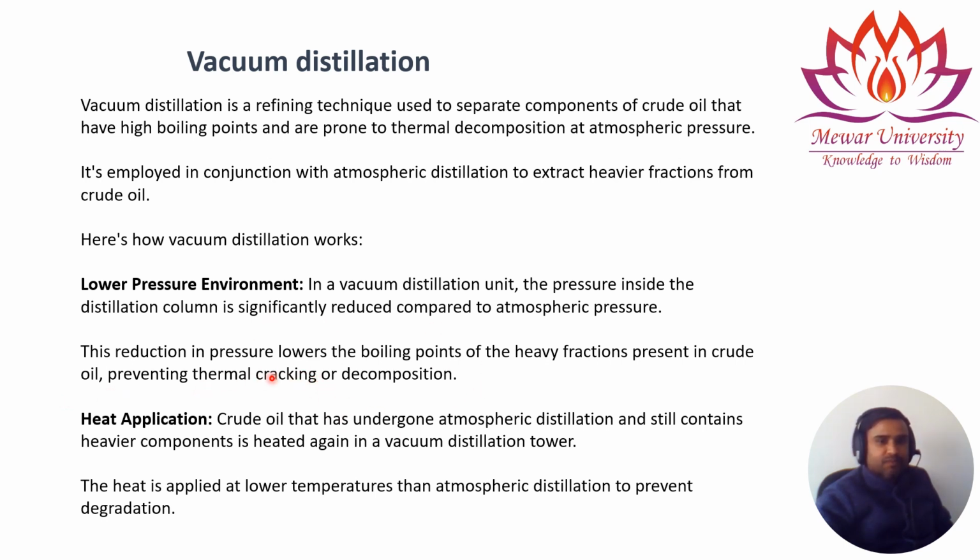So heavier components have higher boiling points. Due to the reduction of pressure, the boiling point is reduced. That's why vacuum distillation is preferred, to prevent the thermal cracking or decomposition of the heavier component products.